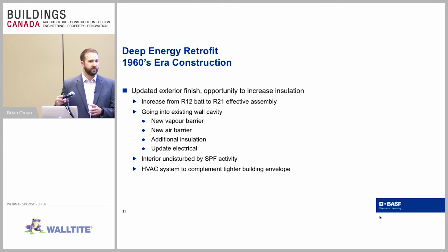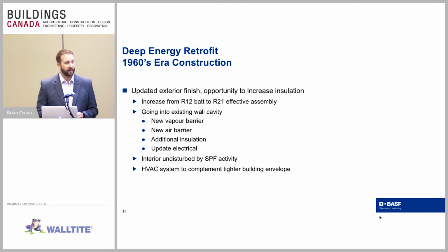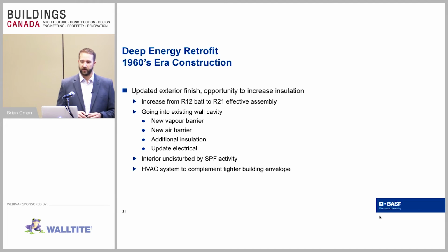If we don't have the mechanicals properly sized to how our building envelope is designed, we can have comfort-related issues. We can actually have energy-related issues as well. Maybe the systems are going to short cycle, or we may not get the efficiency out of the mechanical system. So it's important to bring that into the mix when we're looking at a retrofit like this.